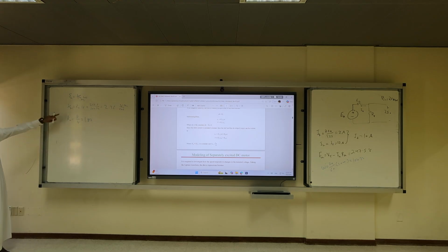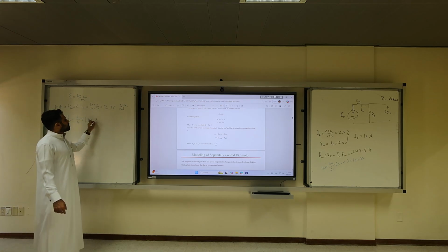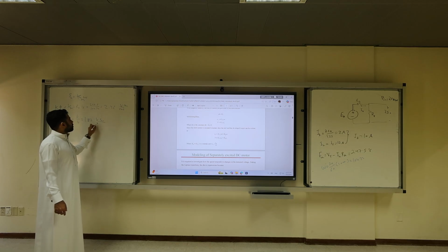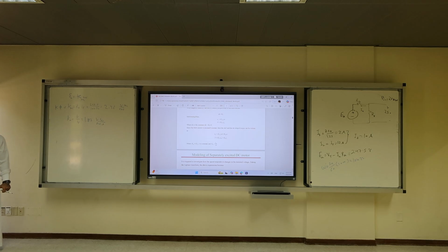However, I am more leaning toward this constant because this is the same one we're going to use in the project. This is Km, which is equal to K times the flux. Clear? So this is the motor constant with the field. Without the field it is a smaller number. Both are correct. What's the unit of this? Volt second over radians times amp. Please don't confuse yourself.